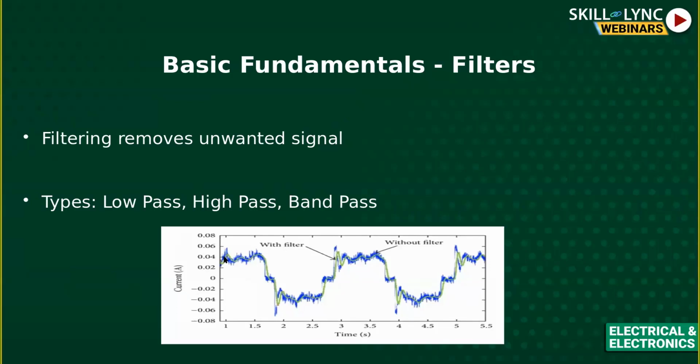The one that you see in blue is the raw captured data from, let's say, an ADC. Obviously you can see there are a lot of spikes here, which is quite common in a real world sensor capturing a signal. But with so much noise, it would probably not be very useful. So you need to apply some kind of low pass filtering here in order to remove this noise.